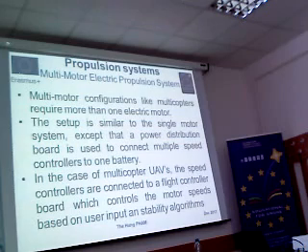They will use some algorithm, for example PID or a non-linear controller, to get the information from X, Y, Z, and the desired states X, Y, Z, X dot, Y dot, Z dot, and even the angular position and angular rate, in order to calculate the right outputs F1 to F4 and apply them to the rotors to get the X, Y, Z, and yaw position of the rotor.